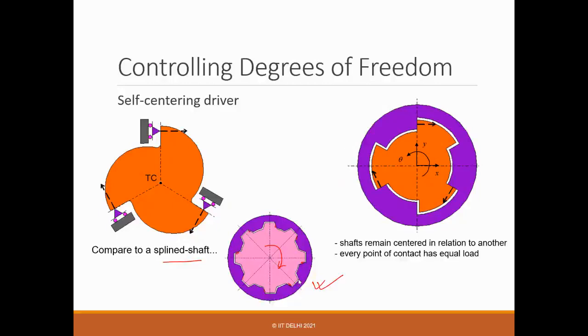But when it comes to precision, then you don't want to go for averaging, but you want to go for a deterministic design. You want to know exactly where it's touching. In this case, for centering of a shaft with this kind of surfaces, suppose, exaggerated, you make only 3 surfaces, radially going this way, radial surfaces meeting at the center.